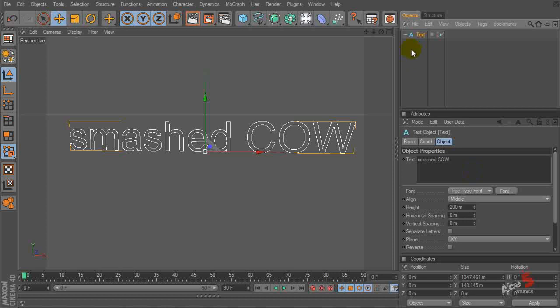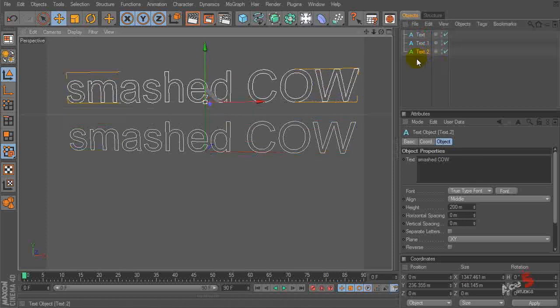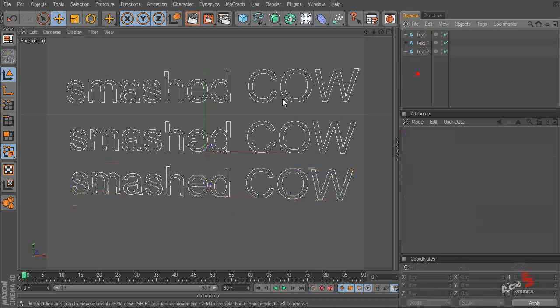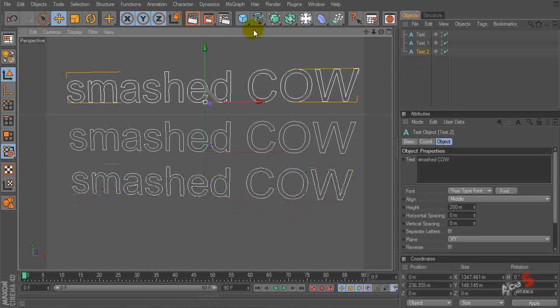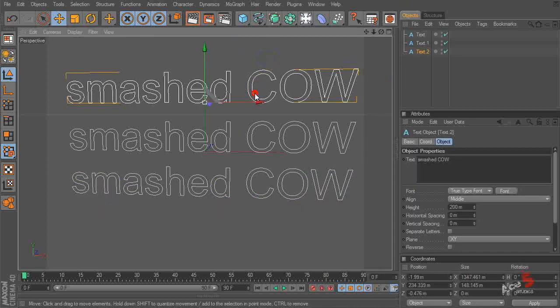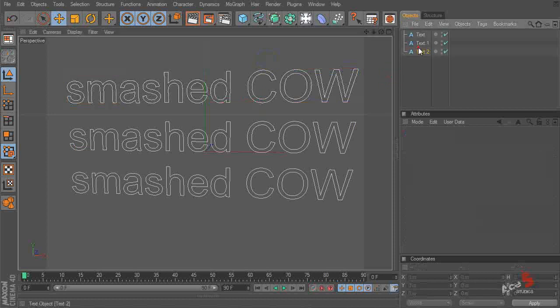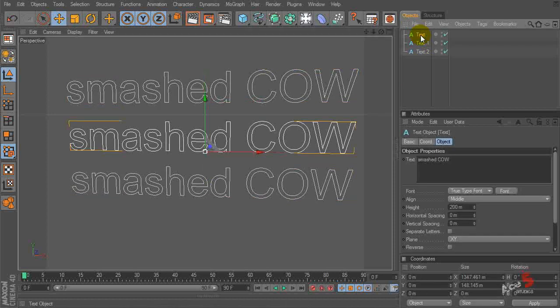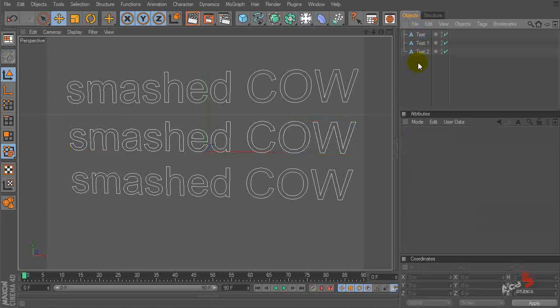So if we have a couple of these texts, just click and drag, and then control click and drag to copy if you don't know by any chance. Now, if I want to select one and, for example, put it into a Hypernurbs or something, I have to actually click on them to find out which one I want. Like I have to select them here to find it, which is rather inconvenient. And more importantly, it's just difficult to tell them apart.